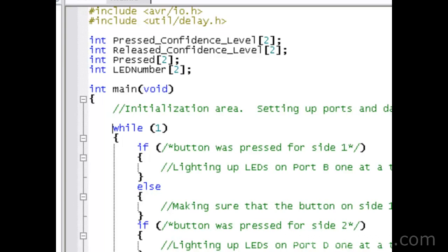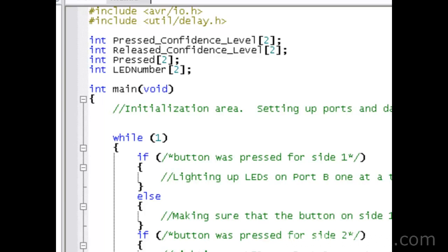So we will start out with defining our data direction registers for port B. For code compactness, I'm just going to go ahead and write this in binary form. So DDRB, we know that's data direction register for port B, and that's going to be equal to, I'm just going to go ahead and make it equal to B0 because I know that pin number 7 is going to be input, and then the rest of them are going to be output because those are the LEDs. So let's do 7 more ones.